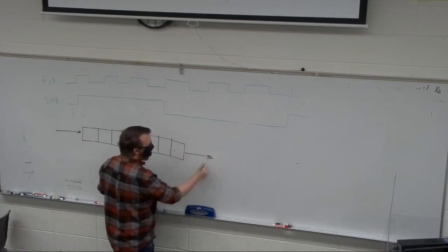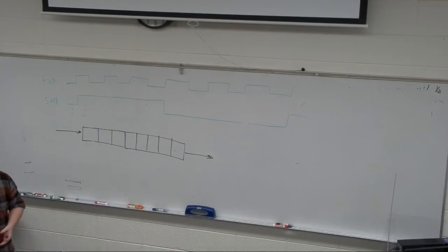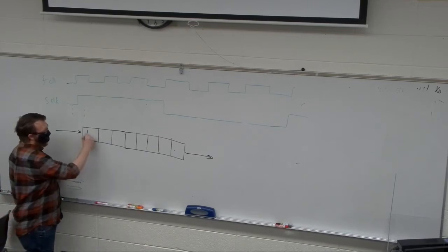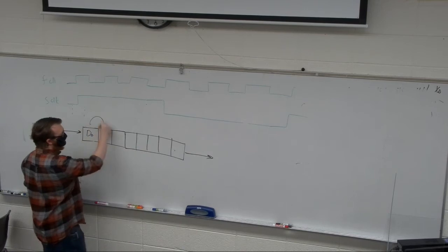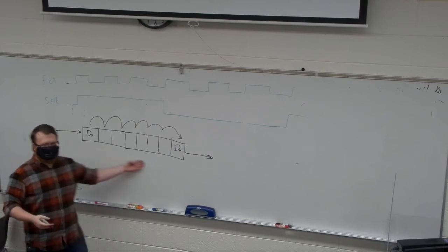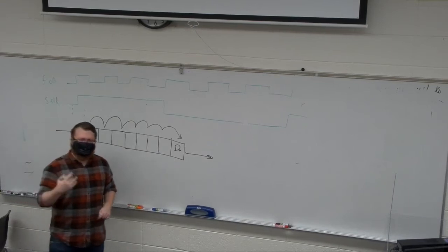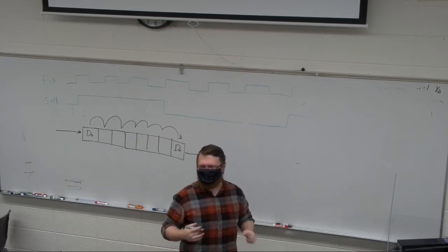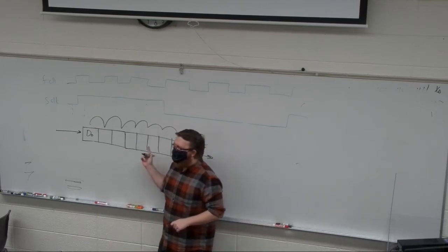So the general thing that we have an idea of that is easy and intuitive is the shift register, right? Where if on clock 1, I put data into here, then 8 clocks later, it will bounce along and end up here with D0 to be read out. The issue now is I've lost 8 clock cycles. 8 clock cycles isn't really a big issue. But again, what if I'm trying to store data in the hundreds of kilobits range? Then that delay might actually be problematic.